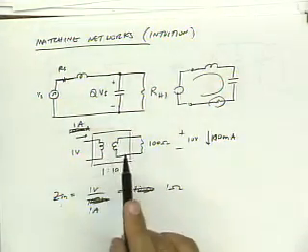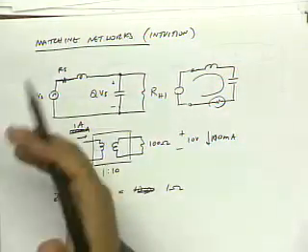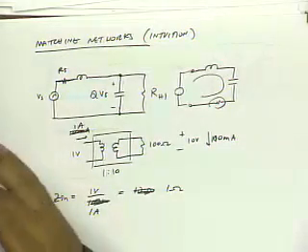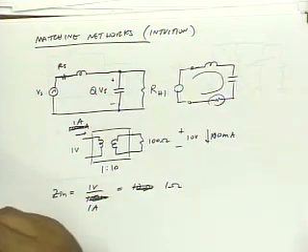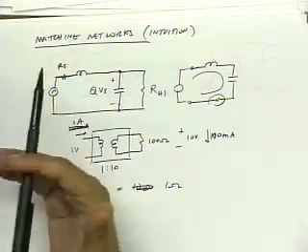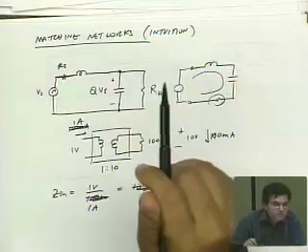And intuitively, you would say, well, if it boosts it by Q, then it should go up like Q squared, right? So if you didn't do any calculations and you said, I have a circuit that can boost the voltage by a factor of Q, therefore it should be able to boost the impedance by Q squared, or vice versa. That's pretty much what we found when we did the exact analysis. The only difference was it was 1 plus Q squared.